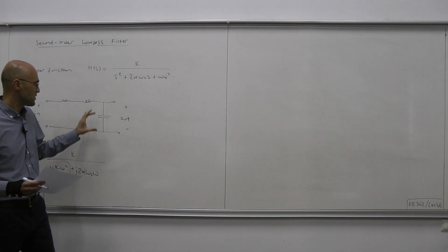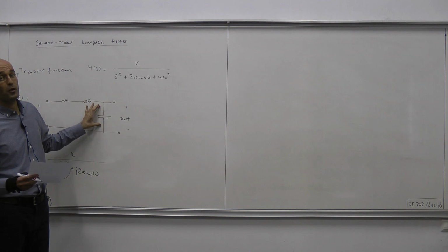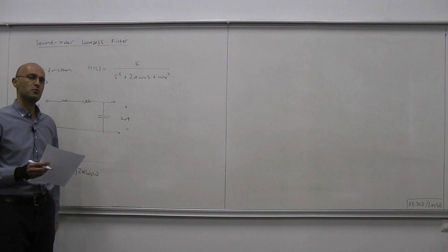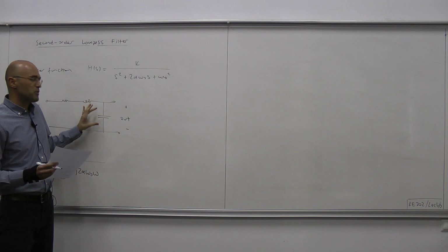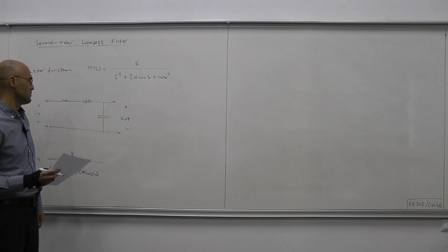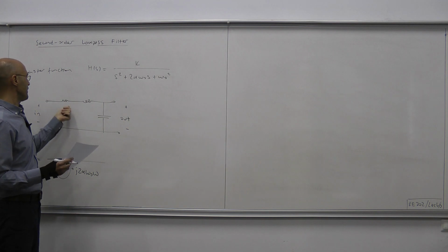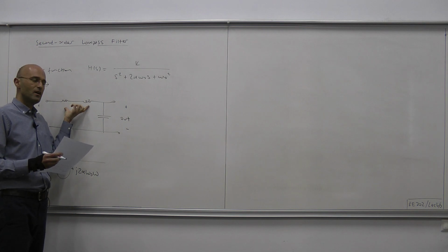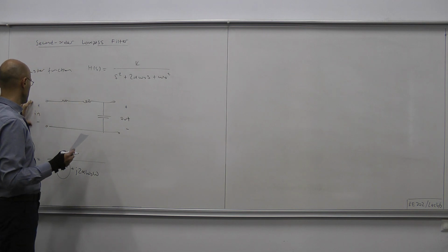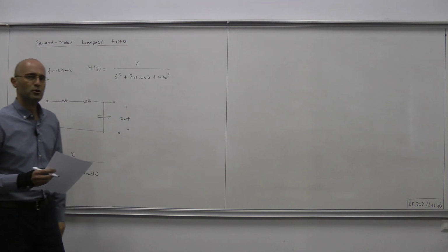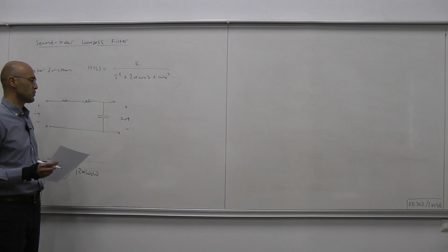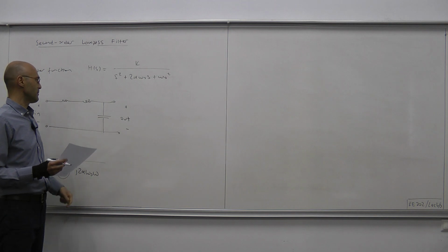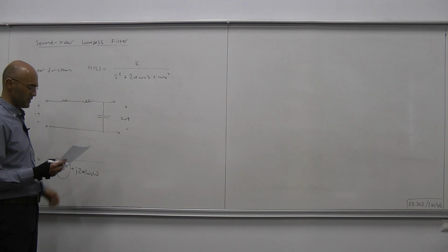So that means at high frequencies the capacitor becomes more and more short circuit-like, and if it's short circuit, clearly we don't see much voltage across its terminals, whereas at low frequencies the capacitor behaves like an open circuit, and open circuit means there will be very little current flowing over this resistor and inductor. That means there will be very little voltage drop across here, so most of the input voltage will appear as the output voltage. Okay, so it's clear that this topology produces a low pass characteristic, and since we have two dynamic components, it's a second order low pass filter.